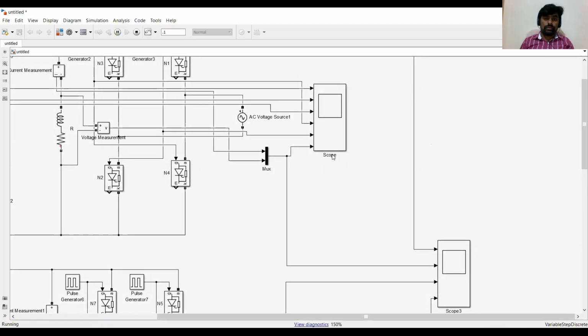So this scope is for 30 degrees. So here you can see this is 30 degrees, and now there is a change in the output voltage and output current wave shape. You are going to observe there is a lag in the current with respect to voltage. Then you can see the negative peak here, and this peak is due to presence of inductor.